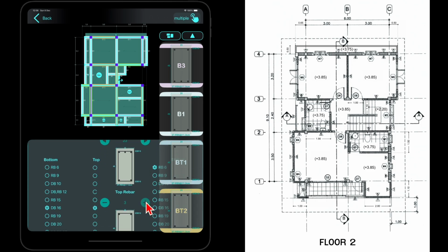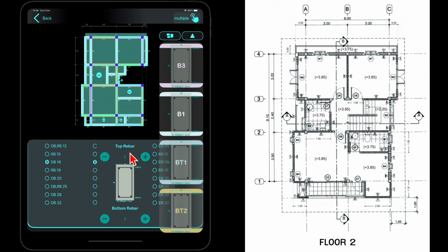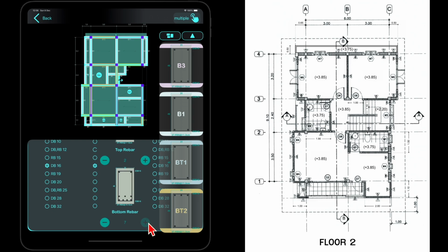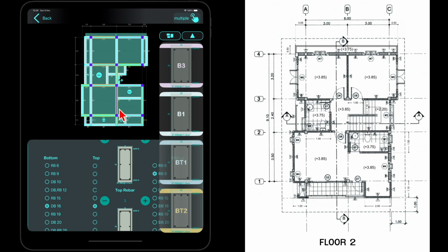This reinforcement system is designed to ensure safety. If the tensile reinforcement increases to a point where concrete failure might occur before the reinforcement yields, the program will automatically increase the compressive reinforcement to prevent such scenarios. Additionally, it will not reduce the reinforcement below the calculated minimum values.